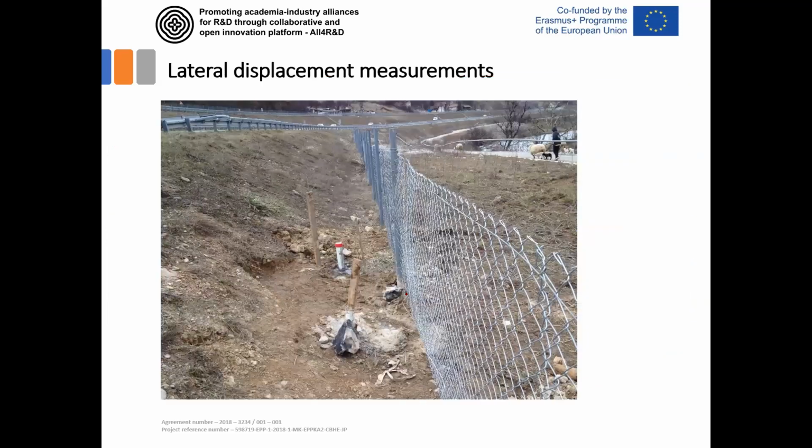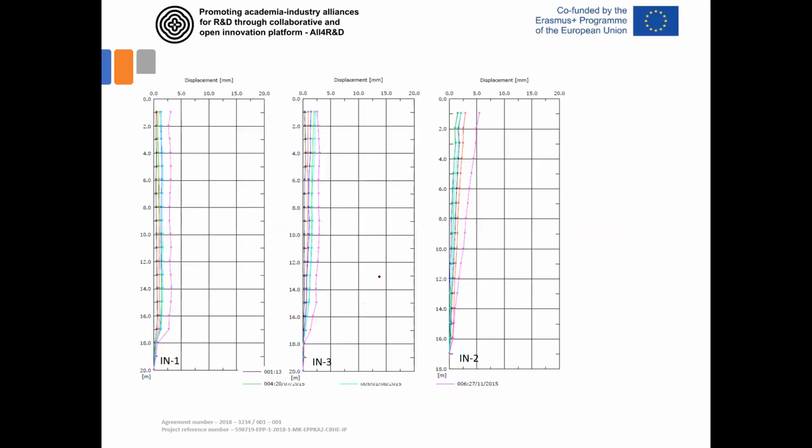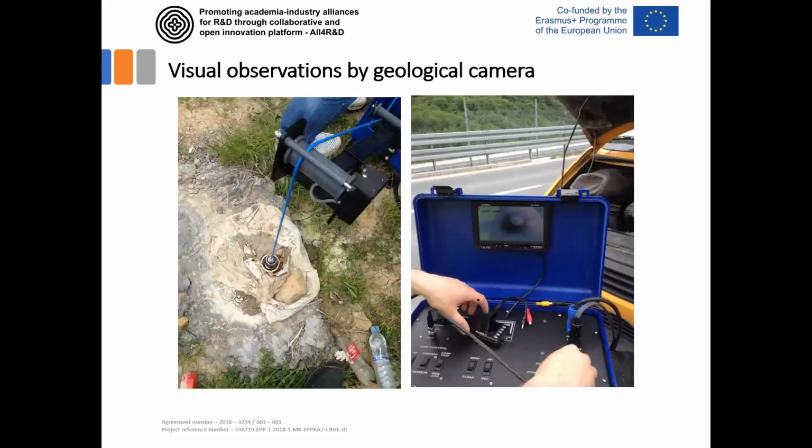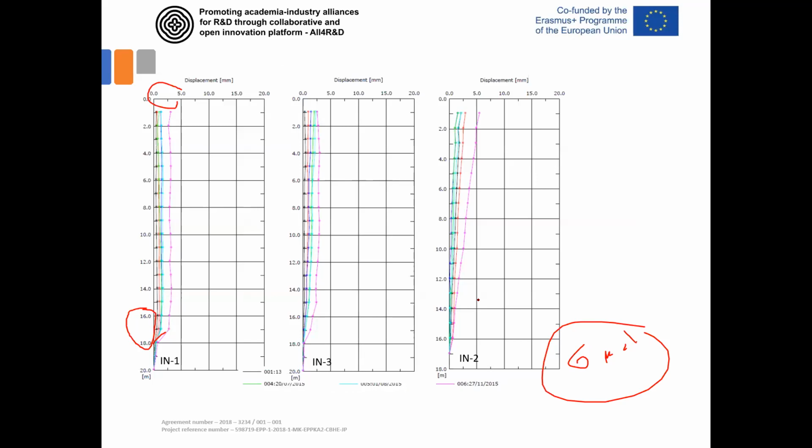When we look at the inclinometer casing, this is the inclinometer casing installed in this borehole just below this embankment of the highway. Some increment in displacement occurred at depths between 16 and 18 meters. The displacement is around 5 millimeters, so very small displacement was observed in the period of about 6 months of measurements. What I didn't show here are the results collected later, maybe during the last 2 or 3 years, that is, after 4 or 5 years of measurement.